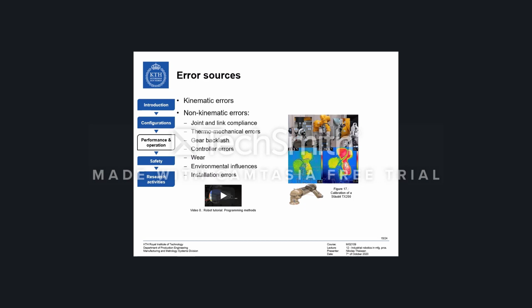Then there's wear, which can just come from the adequate or inadequate operation over time, meaning that the before named characteristics degrade, or simply coming from installation errors, meaning that you have installed your robot on a foundation which in itself is less stiff than the industrial manipulator and leads to a part of its movement.